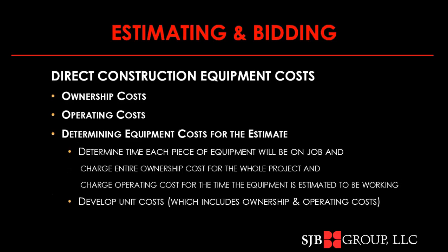When we're looking at our estimate, we need to determine the price of each piece of equipment and what it will be to the job. As long as that piece of equipment is on the job, it needs to get the ownership contribution for every single day that it's on the job, whether the piece of equipment's in use or not.